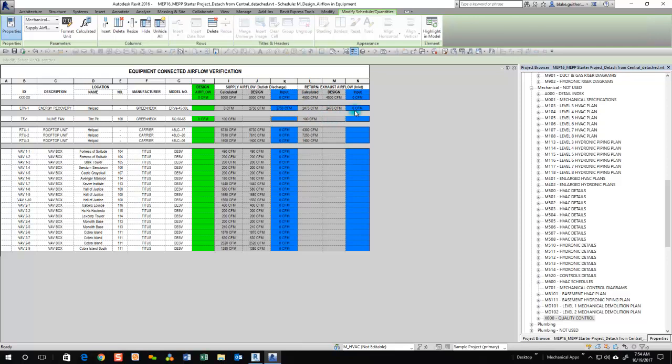The reason this is also important is with air handling unit systems, if you're talking about peak or block airflow, the connector is going to show the peak or connected airflow. If you're designing off of a block airflow, then you need a way to override that. So that's what the inputs are there for. So all of the families function in this sense.